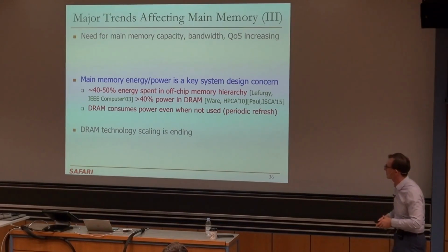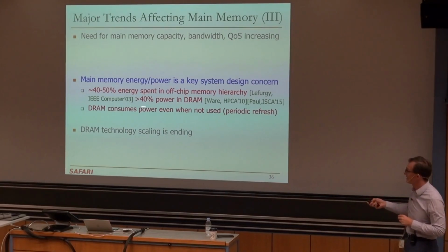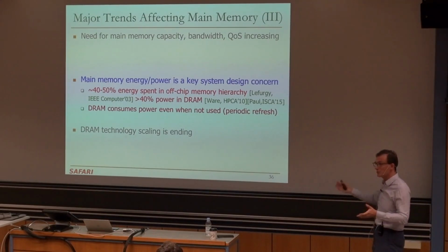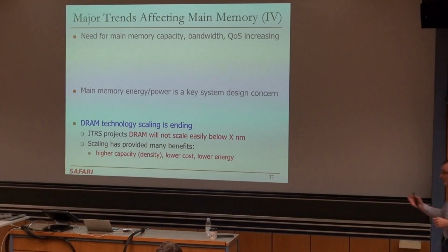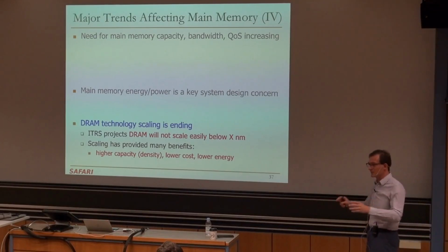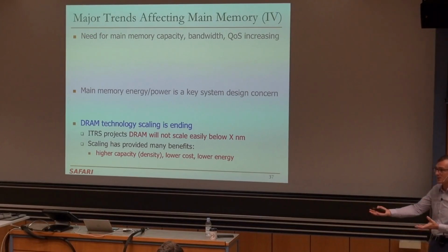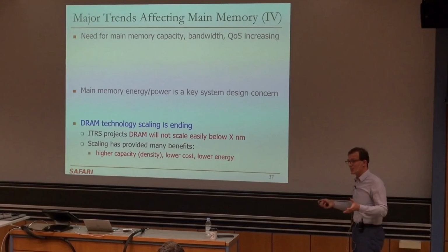Also, applications are intensive as well. And one of the issues that we've discussed that affects DRAM scaling quite a lot is that DRAM consumes power when it's not used. You need to periodically refresh it. So you actually waste a lot of power just to refresh DRAM as well. Okay, so energy and power is another perspective. And I've already given you the relative numbers in terms of how much energy is spent for accessing memory versus doing computation, right? So on top of all of this, technology scaling is also ending.